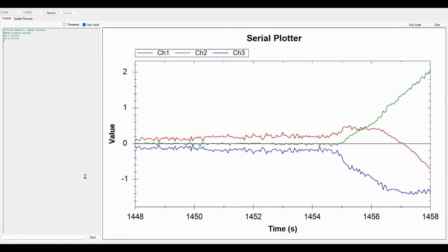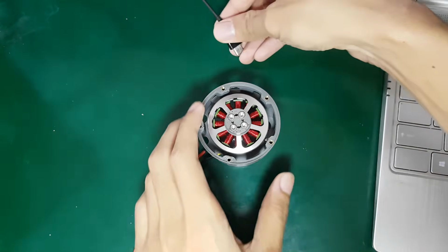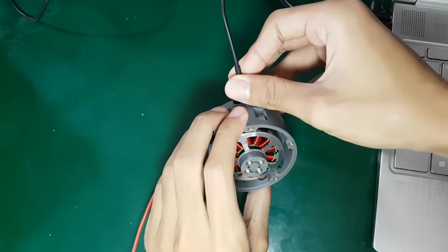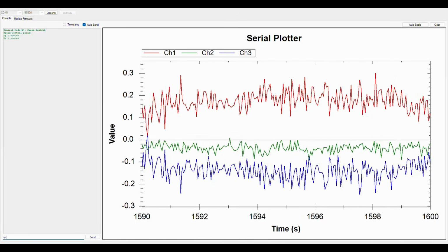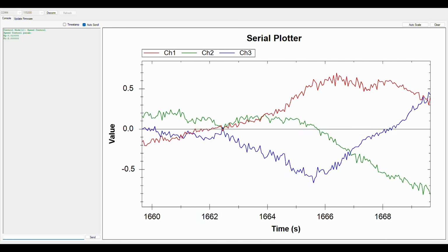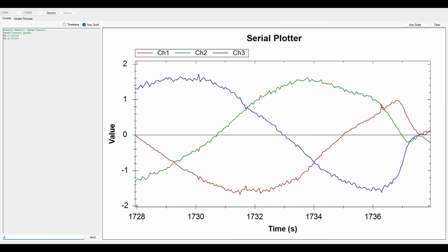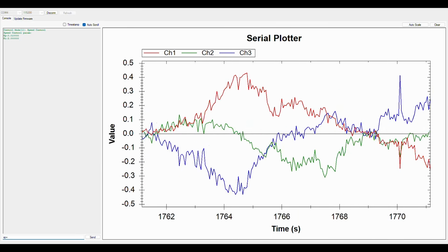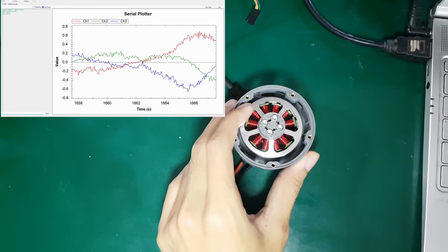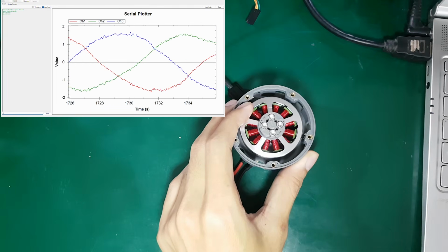I also created a GUI to simplify tuning, using USB CDC as the communication medium. This GUI can display motor response graphs and receive tuning parameter commands. In the future, these parameters can be stored in flash memory to remain saved even when the power supply is turned off. With the implementation of FOC, BLDC motors can be controlled smoothly and precisely.